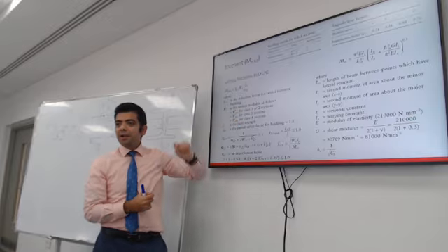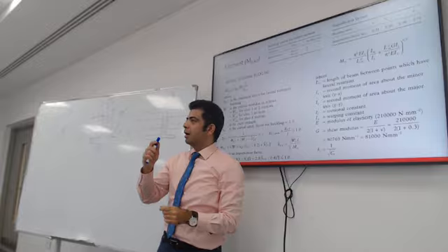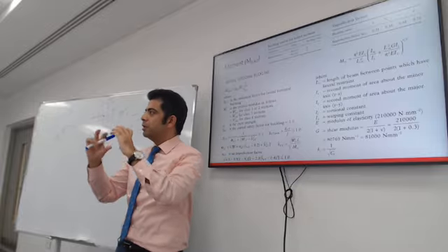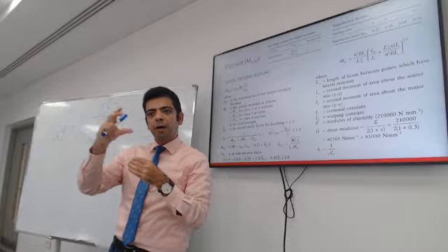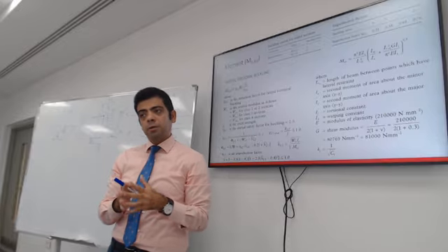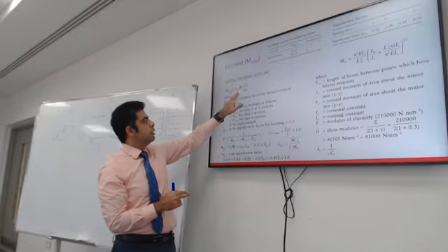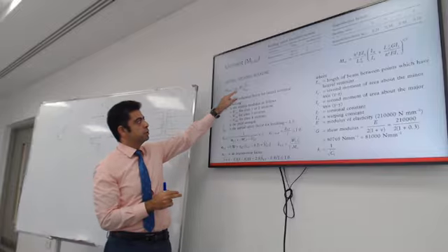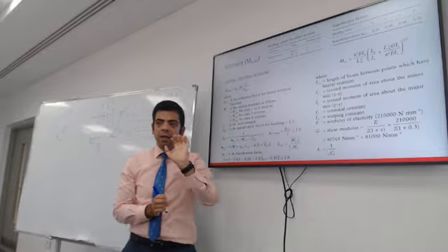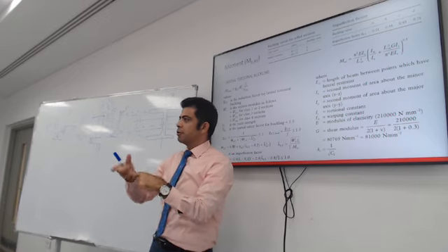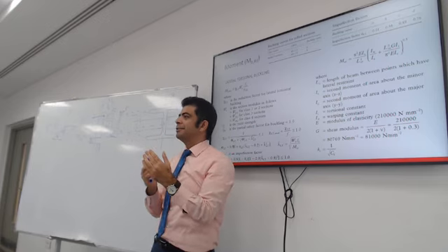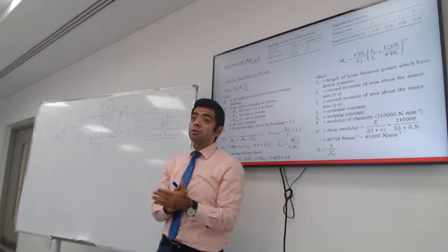Section modulus. It's the ratio between the moment of inertia and the height divided by 2. It has to do with the geometry. So which section modulus do you use? Use it in the strong direction with the moment that is in the strong direction. It's very important to choose the correct section modulus.